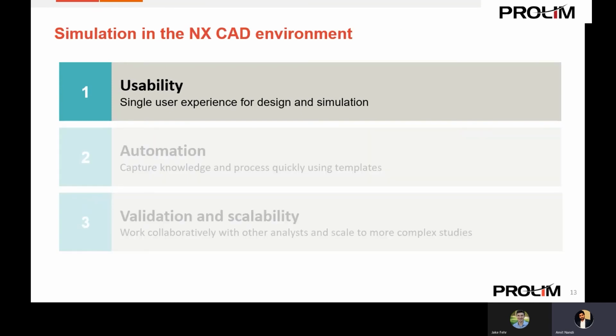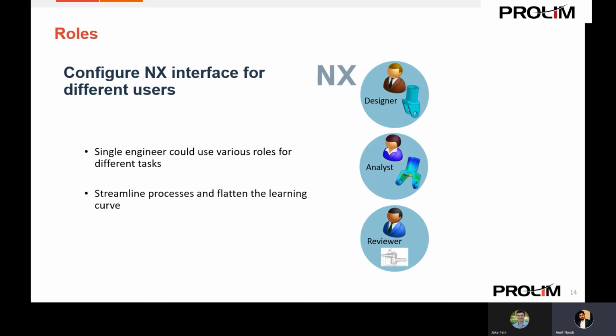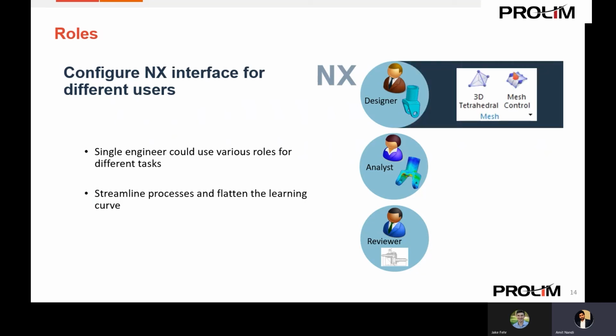So first thing is the usability, right? So we have something called designer simulation, where it is built into the same user interface of NX. Okay, so it's a single user interface between CAD and simulation. So he just has to switch from CAD environment to the simulation environment. So as I said, you can set three different roles in NX.